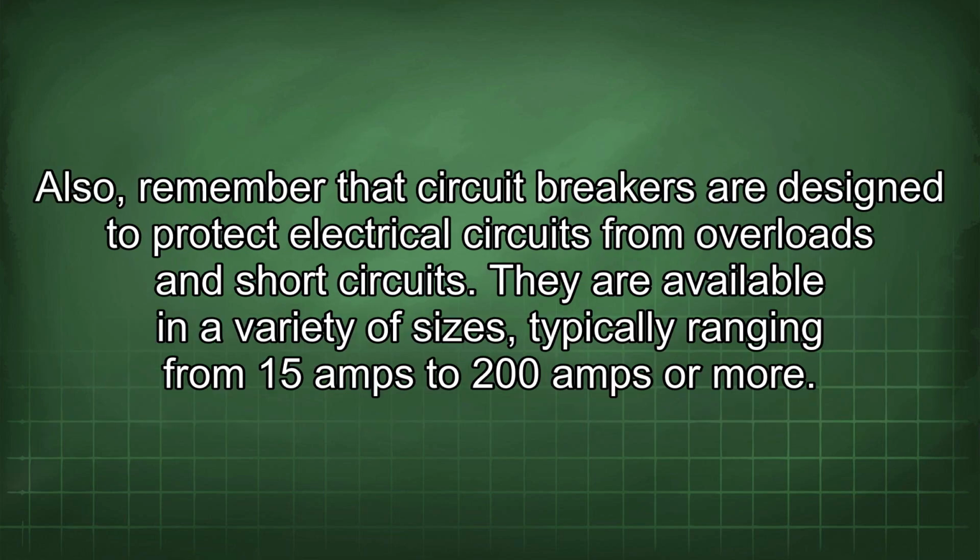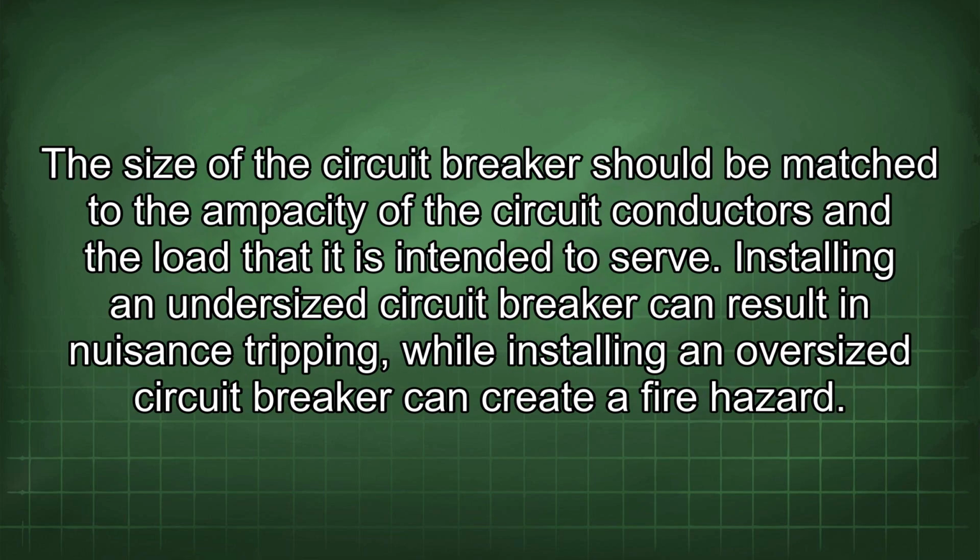Also, remember that circuit breakers are designed to protect electrical circuits from overloads and short circuits. They are available in a variety of sizes, typically ranging from 15 amps to 200 amps or more. The size of the circuit breaker should be matched to the ampacity of the circuit conductors and the load that it is intended to serve. Installing an undersized circuit breaker can result in nuisance tripping, while installing an oversized circuit breaker can create a fire hazard.